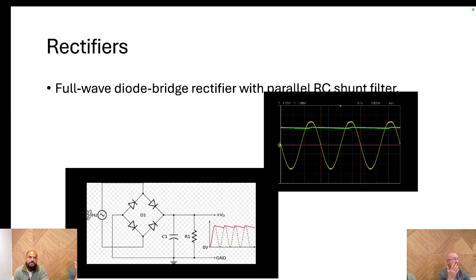And so power supplies are big. We need different voltages, and different current on different components. A lot of times we don't think about all the uses we have for them. But this is what's happening in that little wall wart that you plug in to charge your cell phone. Every single one of those has this in it. It has a transformer, a rectifier, and a filter. And now you know.